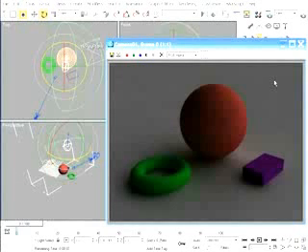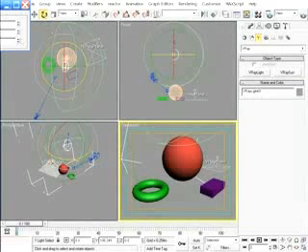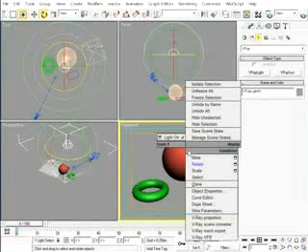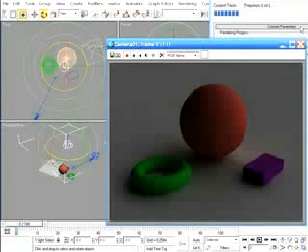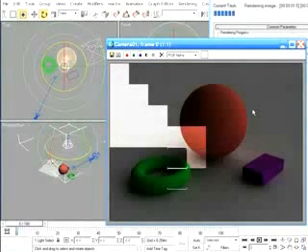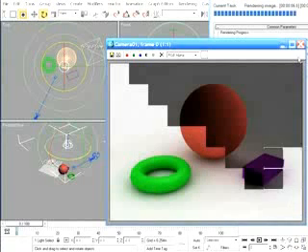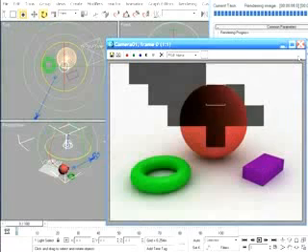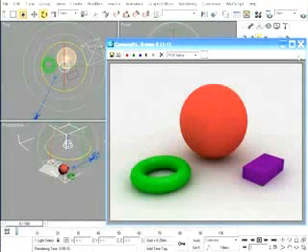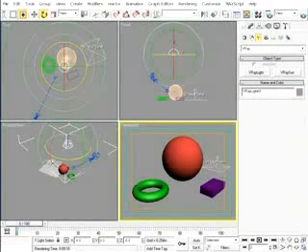As with any skylight, the shadows are quite soft, and when the dome is oriented straight down, it can be difficult to say where the sun in the sky is. Sometimes you may want to use non-descriptive shadows like this, and sometimes you may find it necessary to place other lights in your scene that give you direct light or stronger shadows. Nonetheless, you can see that when we render the dome light oriented in certain ways, we can control quite nicely which side of the scene gets the majority of the illumination and which side is in shadows. And thus, we can better simulate conditions where the viewer knows exactly where the light is coming from.